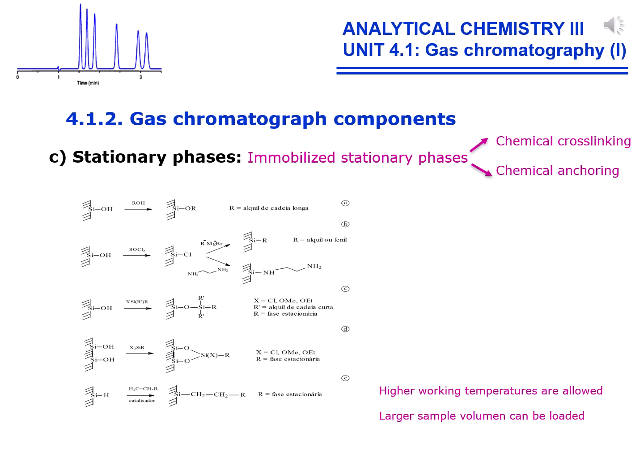To end with stationary phases in gas chromatography, we must say that one of the factors influencing the upper limit temperature of the stationary phase is the tendency to be entrained by the carrier gas stream as the viscosity of the phase decreases with temperature. This effect is particularly important in the case of capillary columns.